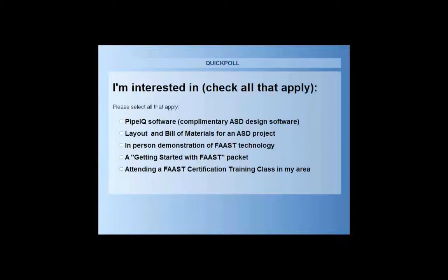If a project is looking for point identification, obviously we have spot type detectors that are listed for very early warning in those environments, depending on the panel manufacturer. But in this case, obviously a spot type detector couldn't be used in the cell because it could be tampered with. So that's why they chose to go with one device per cell.